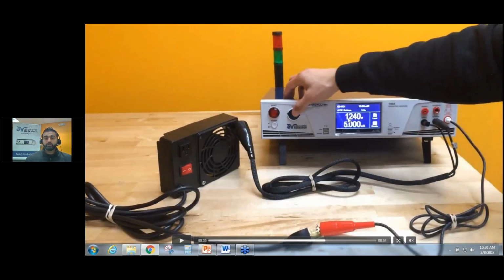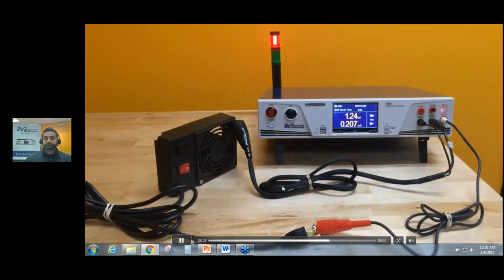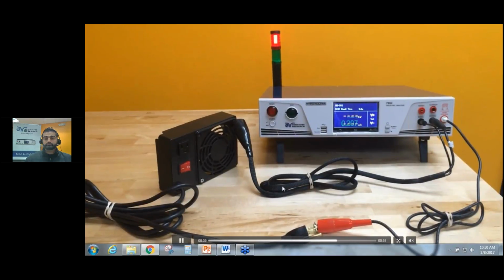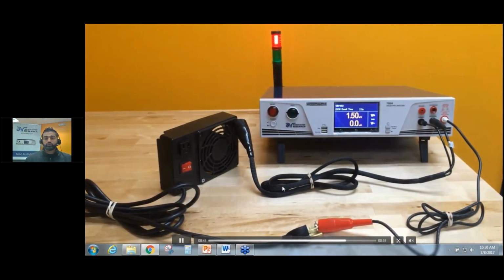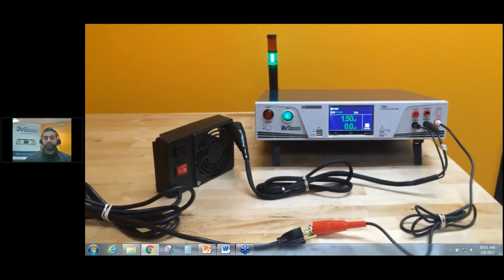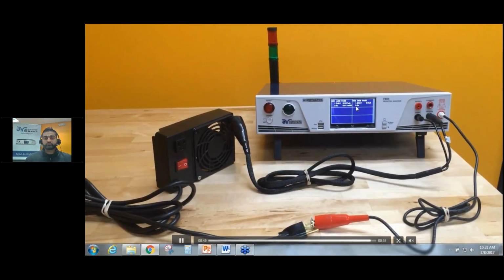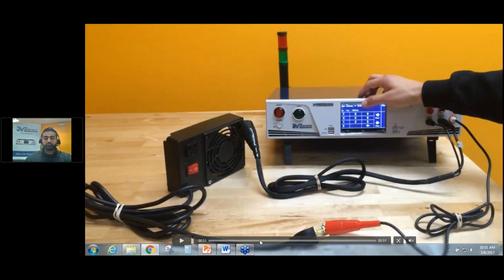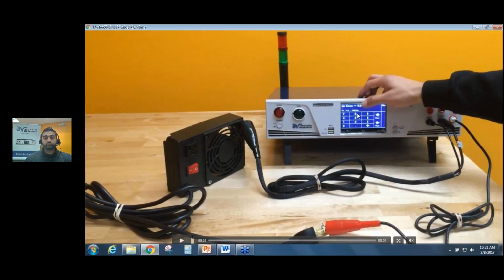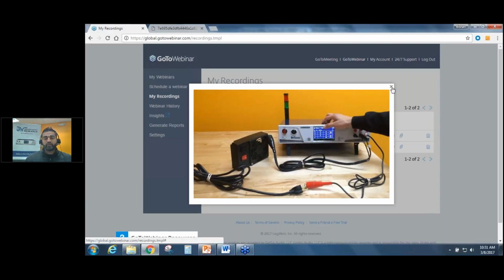Again, in this case, we're going to apply 1240 volts. Our high limit is 5 milliamps. I want to make sure the leakage through this does not go beyond 5 milliamps. So we'll talk about the results. We did an AC test, a DC test, and a DC test is performed in a similar fashion, so no connections are changed. Only the leakage goes from milliamps to microamps, due to the nature of how a capacitor acts in DC voltage versus an AC voltage.